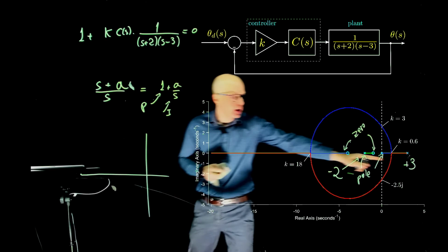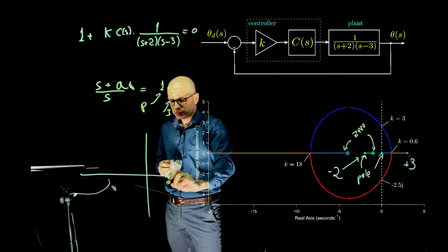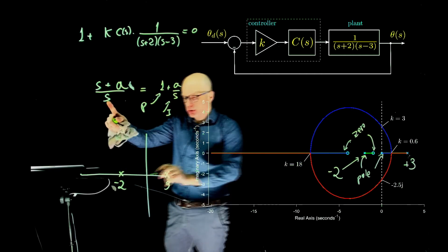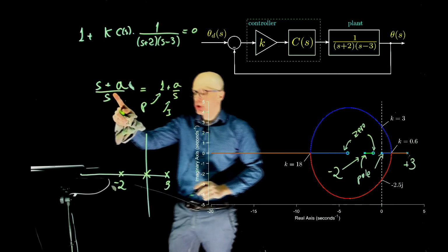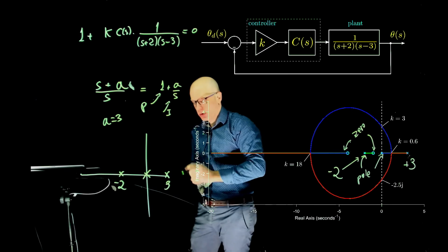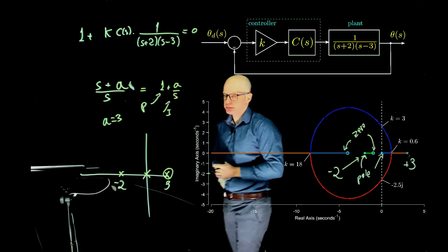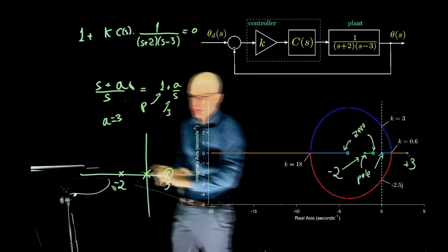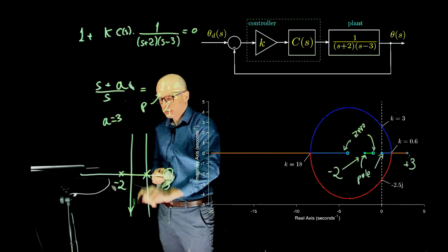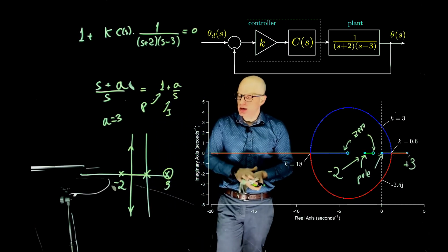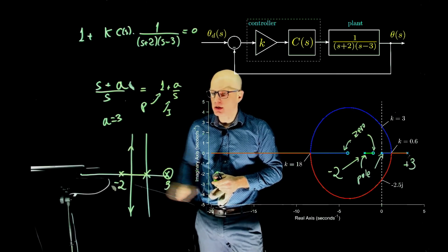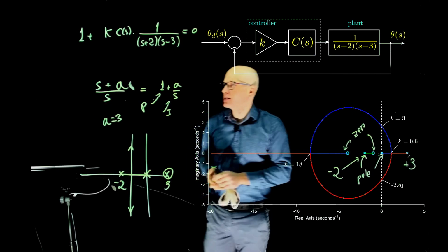We would have the pole at 3. I have the pole at -2. Now we added a pole there. And if we set A to 3, we could place the 0 on top here. So these two cancel out. These two will come together. One goes upwards, one goes down. And now the system is again stable because this unstable pole disappears, and all other poles as k goes from 0 to infinity, this k there, right? Remember that this is C of s.